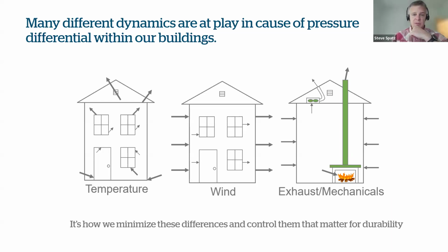and something that we need to be definitely aware of as we modify and retrofit existing buildings. As we start to do things to the building shell to make it tighter than it was originally, that can and will have an impact on the availability of combustion air for boilers, furnaces, wood stoves, fireplaces, et cetera, and the capacity of draft for those appliances as well. So we do need to be paying attention to those impacts when retrofitting existing buildings.